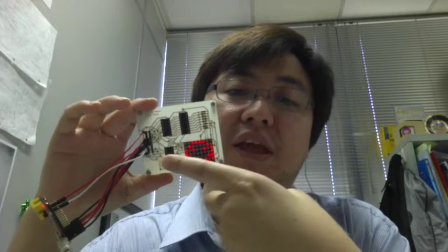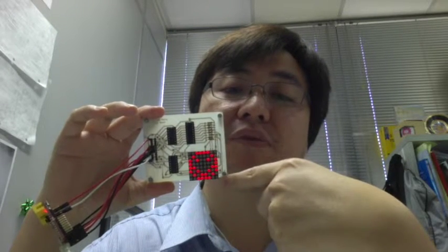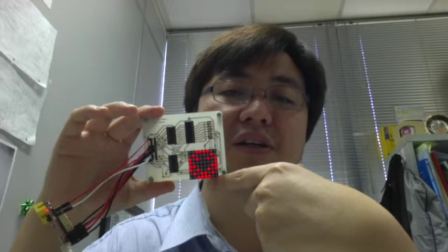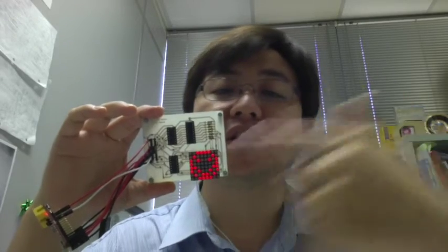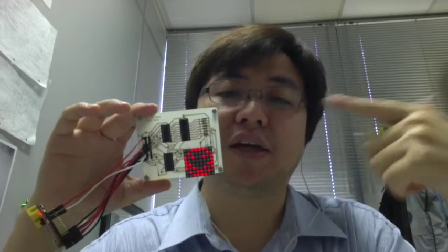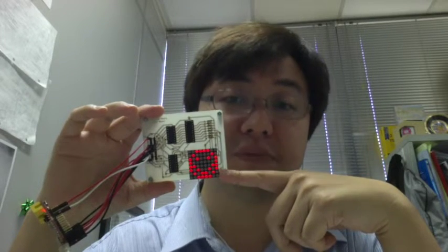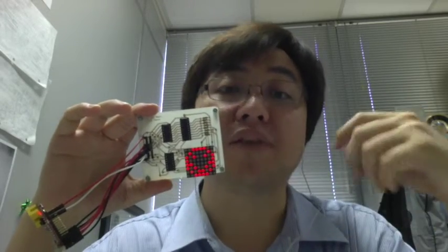You select the LED from row 0 and column 0, and you say you want it to be on or off. Then you switch to row 0, column 1, and you say on or off, and so on. If you keep moving so fast that your eye cannot see, it looks as if they are all on at the same time. But actually they are on and off at a very fast speed. Up to this point, you should be able to do exercise number 2, the fixed pattern.